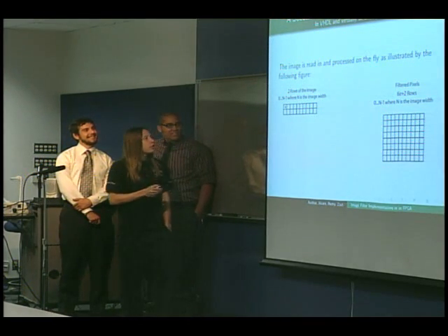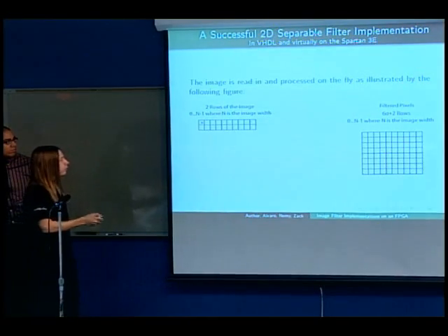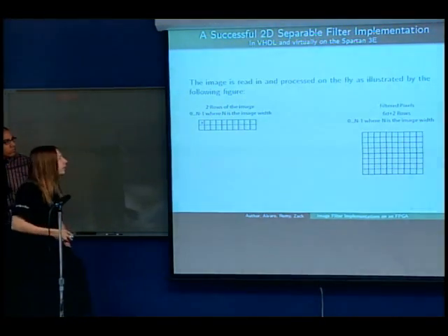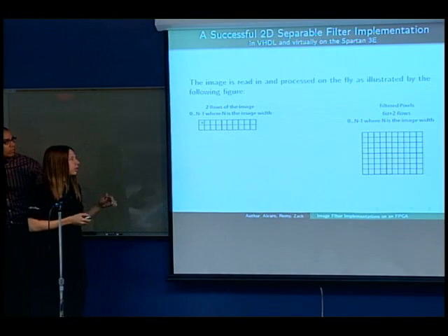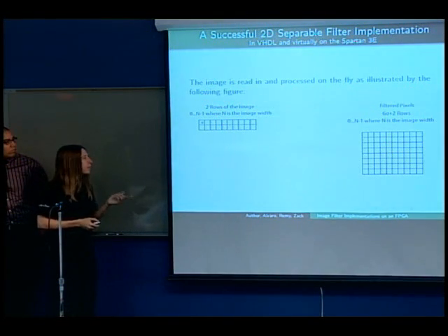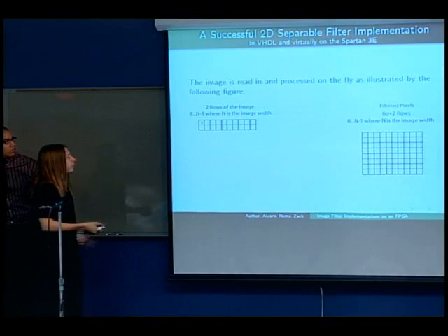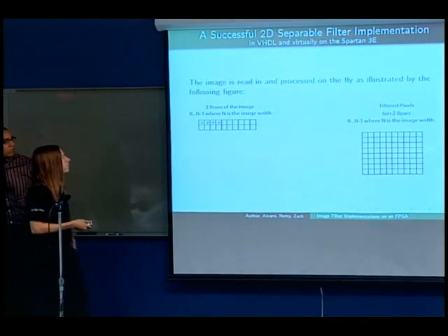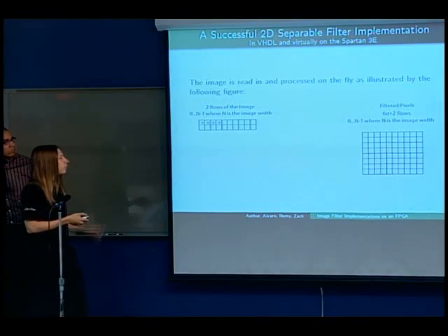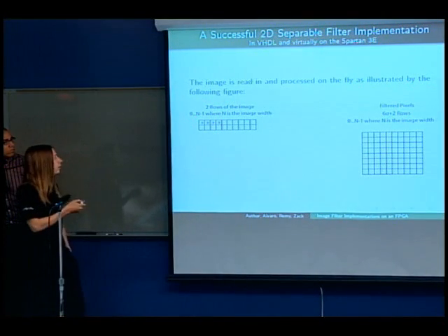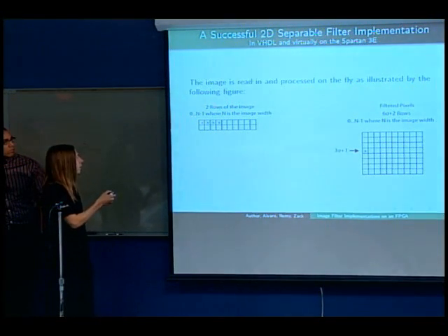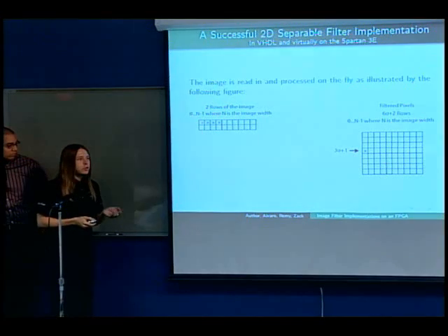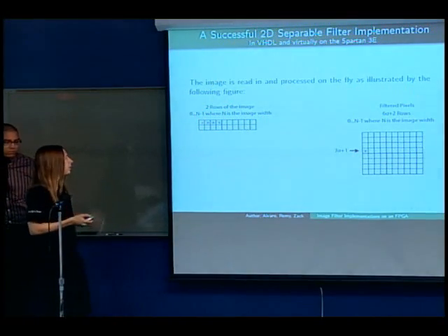So yeah, this is used for storing the horizontal rows, and this is for the vertical rows over there. And the reason we need more vertically is because to do a vertical convolution, you need to get values from each row, whereas horizontal, you do it this way, so you need to store more data. The black X's correspond to pixels, whereas the red correspond to ones that have been processed. So as we get enough pixel values, we can start to process and do all the necessary operations, which includes the convolutions and adding them together and such.